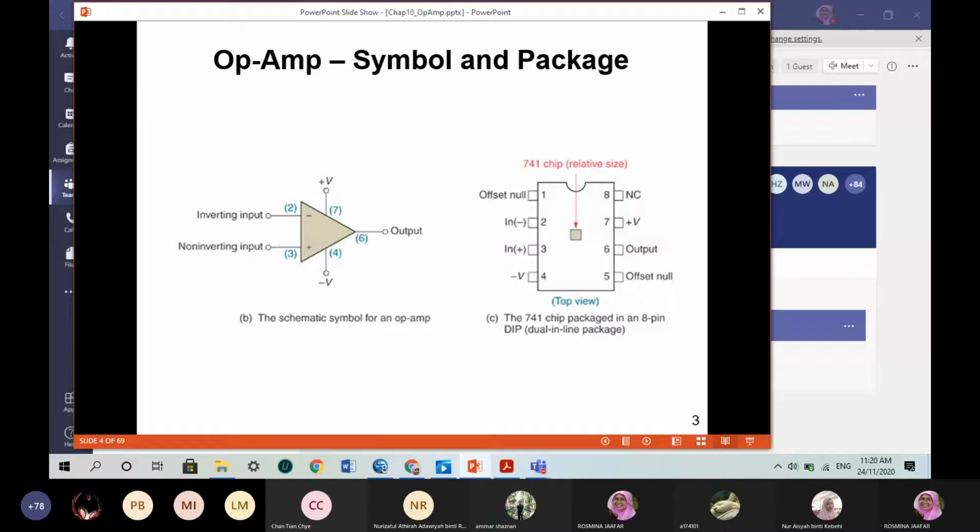Depending on the device's data sheet, you will have information regarding the safe working supply voltage. Here it would be VCC for the BJT inside the circuit. Normally for the 741, the maximum would be 15 volts. If I'm not mistaken, the data sheet says negative 22 to positive 22, but normally we use 15 volts.